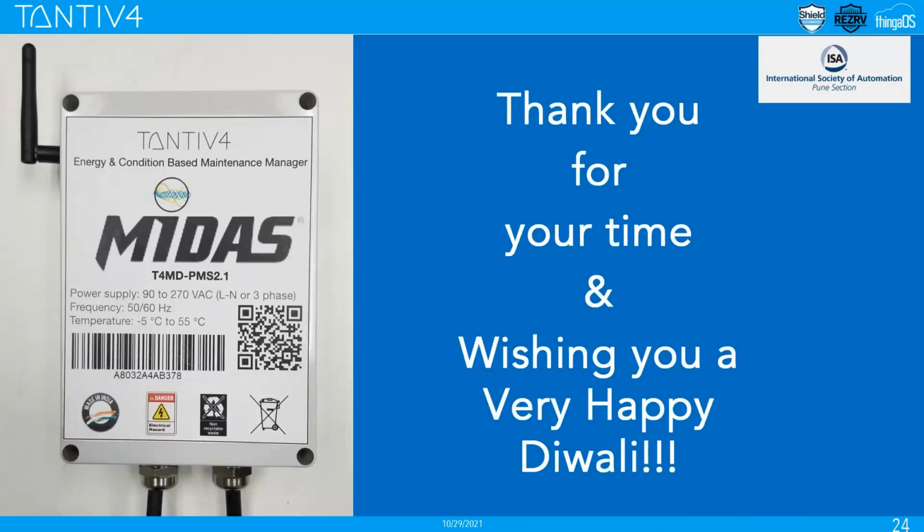We use Rogowski coils, the current transformer and potential transformer CTPT coils, which are connected to the bus bars, and these coils are connected to this device, which has internet connectivity with a SIM and everything, and from there the data goes directly to the cloud. So there is no need for any external internet connection.